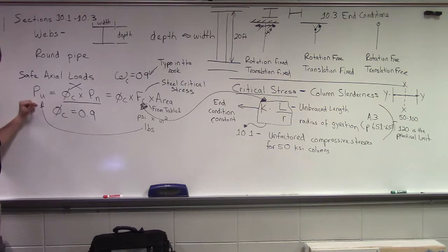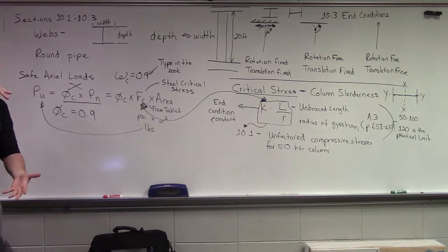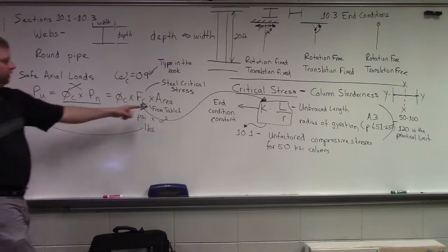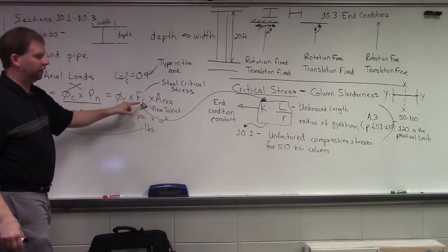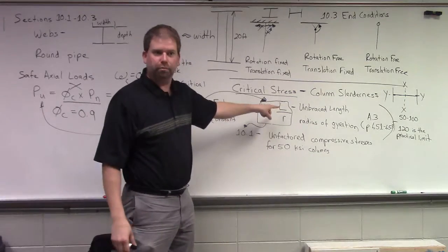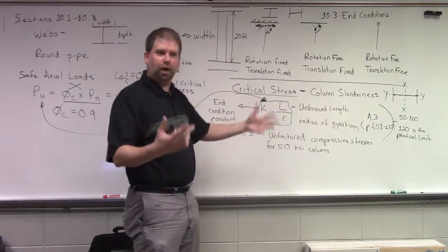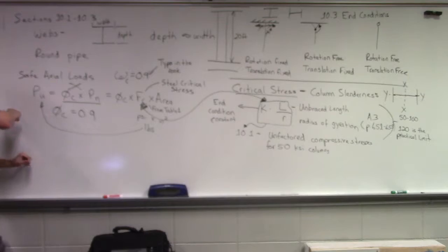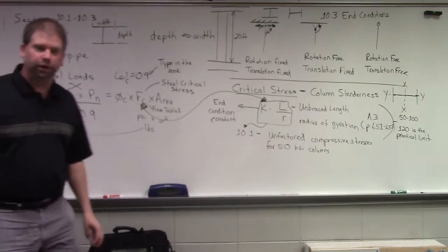Just like way back in the beginning of the semester when we were dealing with an 8-inch wood post, and it's so long, how much stress can it take, how much is it going to deform? There's a couple different ways to go about this problem. If we know the weight of the building, we can plug this in, pick out our steel, and it can tell us this value, and then come back to figure out our unbraced length. But some problems will have you figure this out, then move back and figure out your maximum load that you can put on your building.